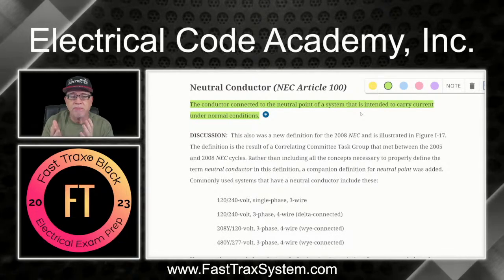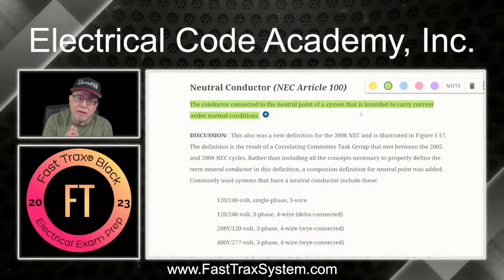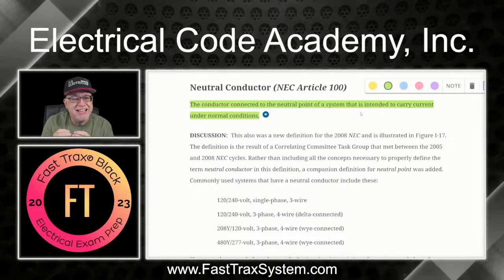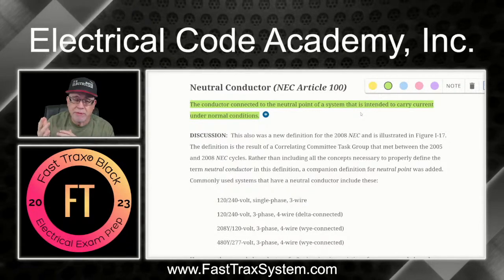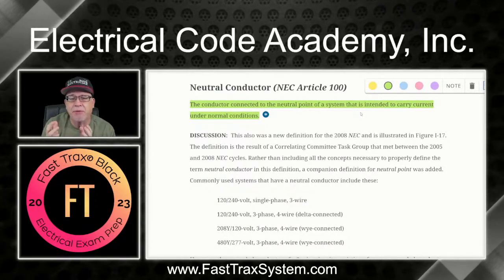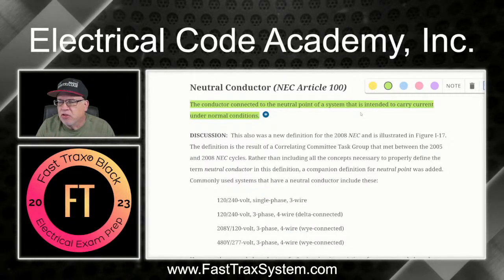Okay, so don't confuse an equipment grounding conductor with a neutral just because they connect together at the same location back at the service. Don't get them confused. The neutral is going to carry current, or is expected to carry current, at any given time under normal conditions, whereas the equipment ground is not, only under abnormal conditions, like a ground fault, okay? All right, so here you go.